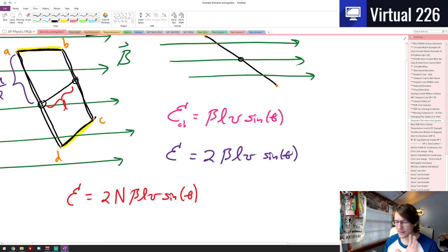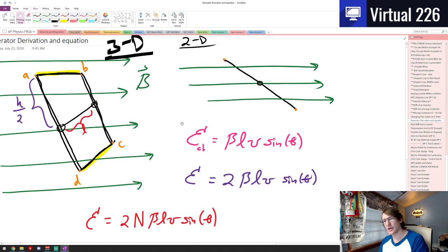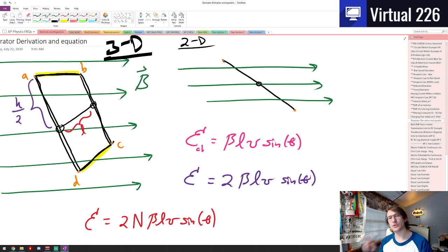Now, this is where things get a little weird. Because our loop is rotating around the pivot, right? Remember the pivot right here? That's what's causing this tumbling motion. Okay, this is our pivot in 2D. Because our loop is rotating, it's moving in circular motion. We can state that the edge of our coil, or our loop, is moving with some velocity in a tangential direction. And if this has a velocity up this way, this velocity will be down here like that, right?